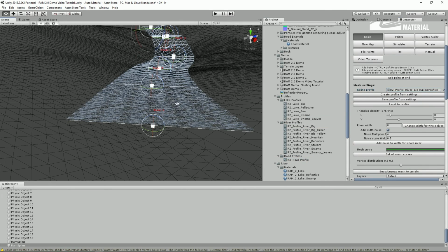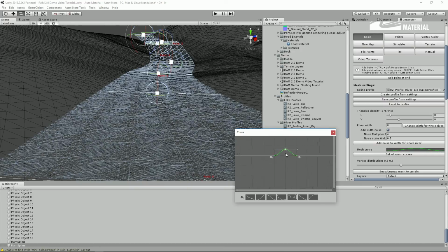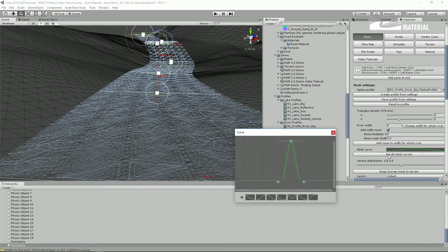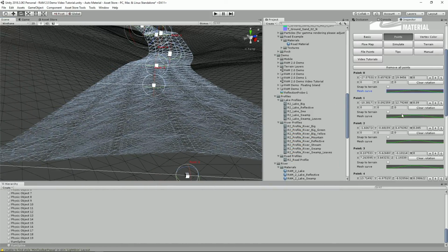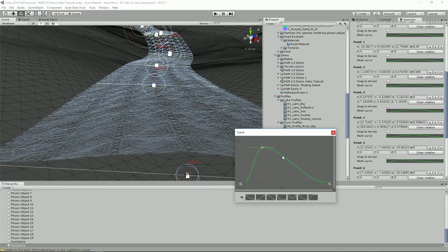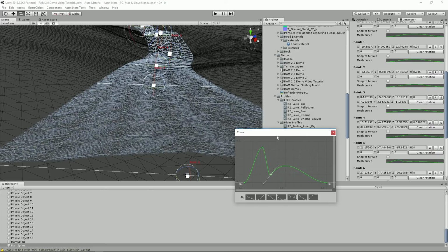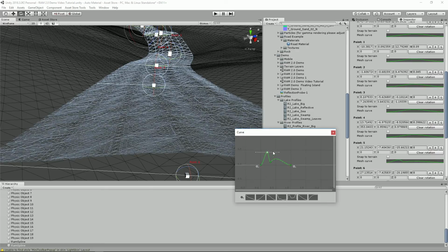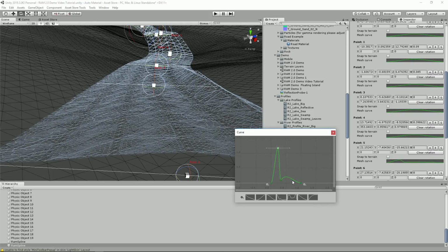If we go back to river, we see that we could manage the whole shape of the spline as well. We simply set all mesh curves. We could do the same per point in the point panel. For example, we'll choose point number 5 and we move the spline. And we see that in real time we could manage the shape of the road or river or any other object that the spline represents. It's very useful. Some people use it even for cliffs.